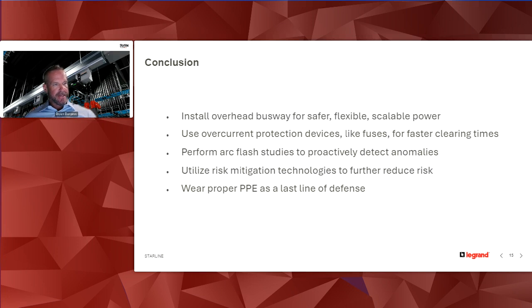And then at the very end of that is where proper PPE is the last line of defense. So all these other factors come into play. And then the bottom line is, obviously PPE is the last line of defense. We want to reduce arc flash risk as much as we can, get it to an acceptable level, and then wear the appropriate PPE. So I think that's it, Gary. If you want to get us into the Q&A, sir.